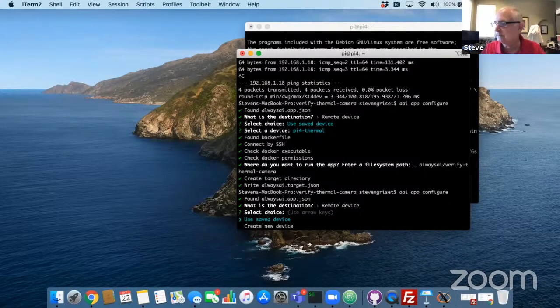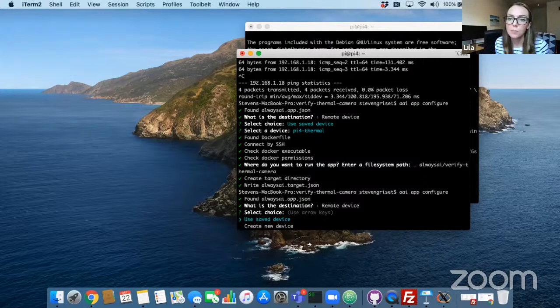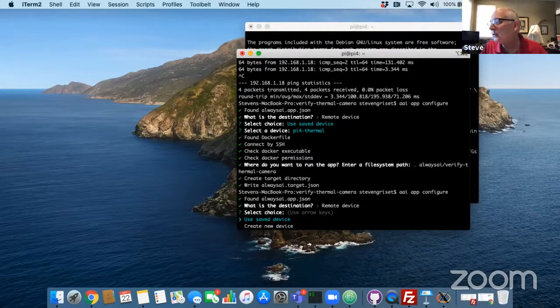Definitely. And then Ross asks, in your experience with the Lepton so far, does the internal temperature of the sensor itself impact the readings? Is there a calibration procedure or like a black body source? No, so that's the great thing about this camera, the way they put the sensor together. That's why it's a little bit more expensive for a camera. The camera itself will not heat up the microbolometer array that's detecting. That's one of FLIR's market advantages. Some cameras don't do that, and they do heat up. So that's a great question.